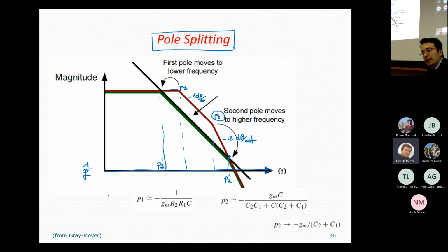Okay. Concerning the maximum value, we have to take into account that this guy should be on, which means here having a VGS due to this connection. This guy should be in saturation and also on.